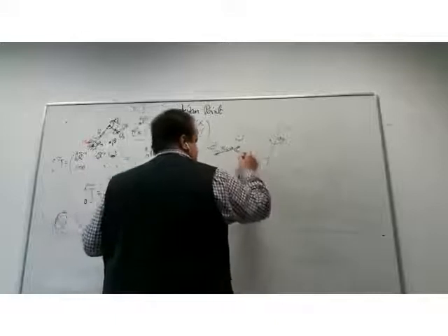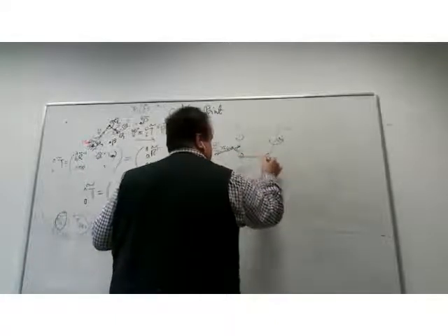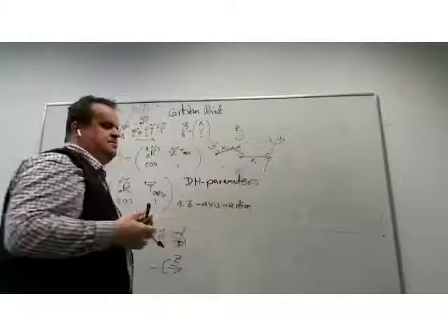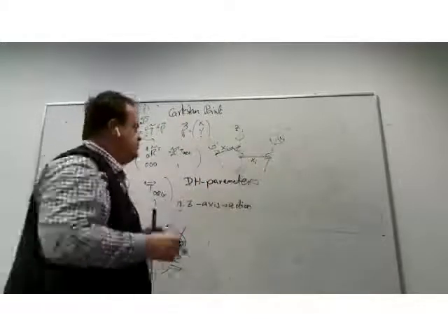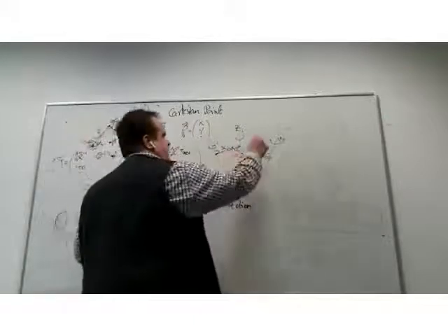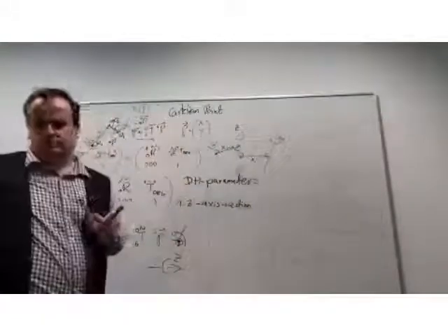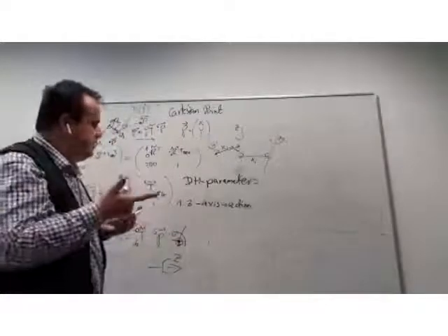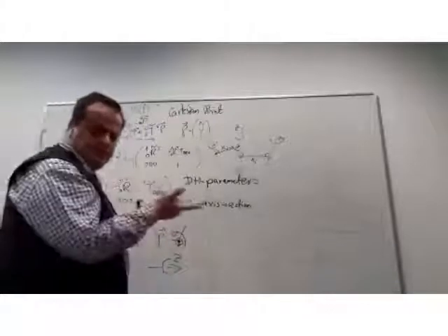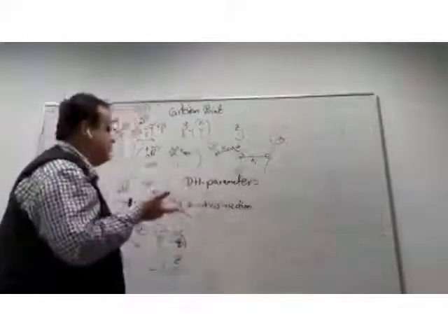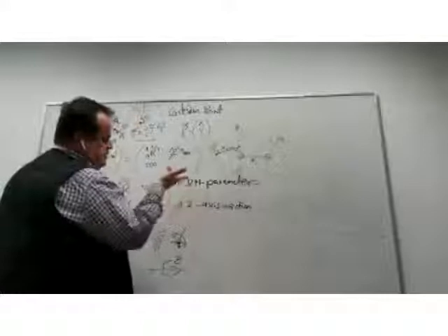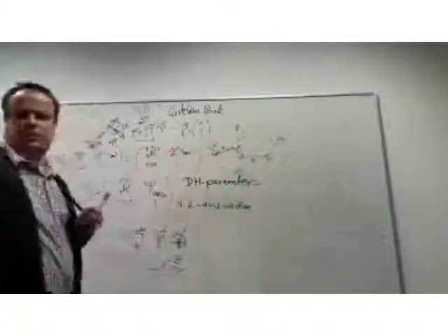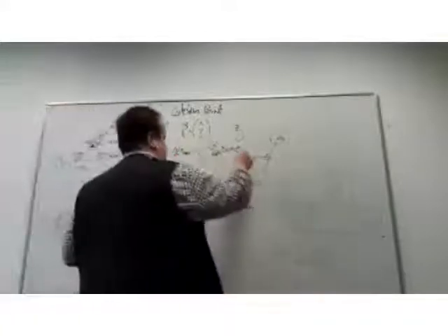The same is true here. This will be the xi. It's basically again the line between zi and zi plus 1. And once I have x and I have z, then I apply the right hand rule, the original definition of our coordinate system: x this, z this, the y would be pointing into the board here, the same as here.